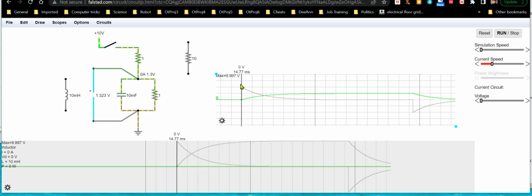But you can see right here, when we were just starting out, you've got a high positive current, and the voltage is increasing as the current drops, because it's charging. But here you get a high negative current, which is decreasing as the voltage is also decreasing. So, those are going to be fairly important to understand.